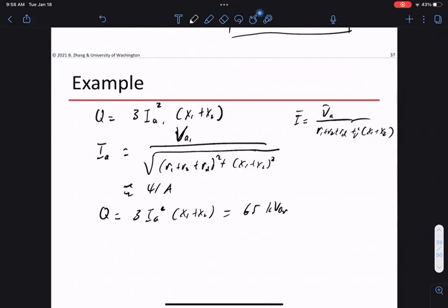Consumed, right? Because you have a bunch of inductors, but the generator only supplies active power. So this is always consumed by the generator. Again, the generator is a negative resistance that does not provide reactive power. These inductors consume reactive power because current flows through them, so this is supplied by the grid. The grid has to supply reactive power for this generator to work.